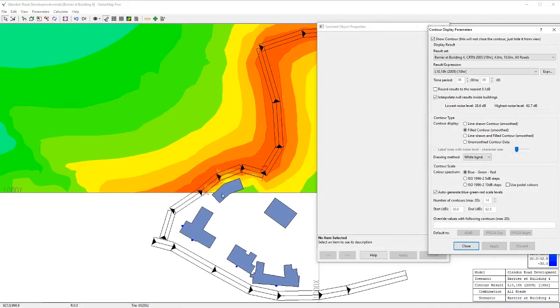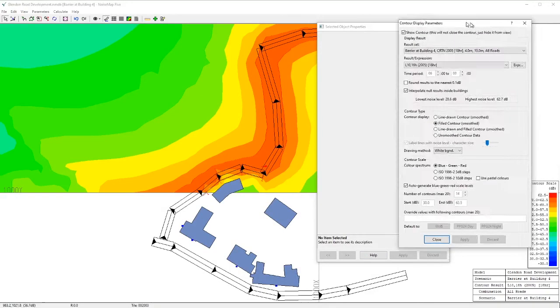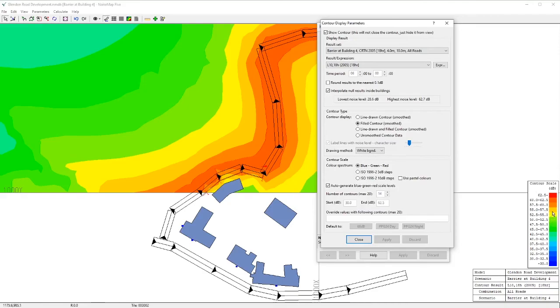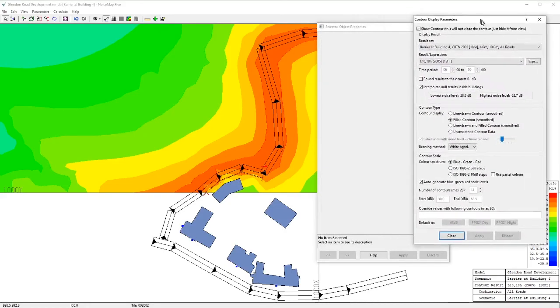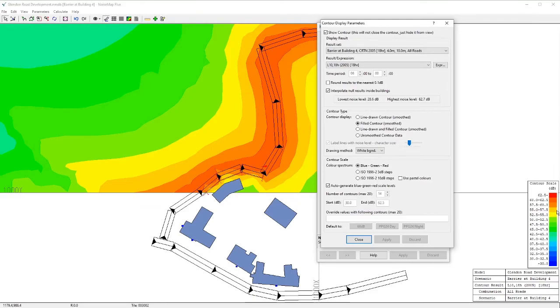What difference has that made? Well, you can see the noise levels have actually gone up a bit, which is exactly what we would have thought. So that now the orange levels are touching the buildings here and here. That's 55 to 57.5. And well, we're moving up, aren't we? But we're still only 57.5-ish there. And in fact, well, we don't need such high barriers. Well, I think that's enough for now, but in the next episode we'll look at how we can make some further refinement to the barrier heights to get even closer to the design target.